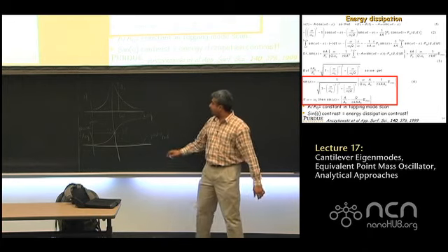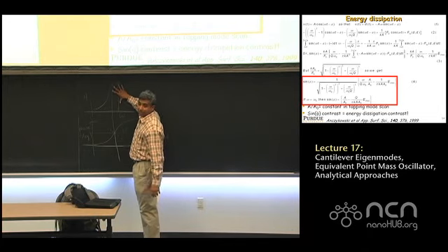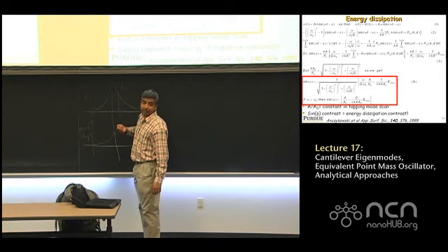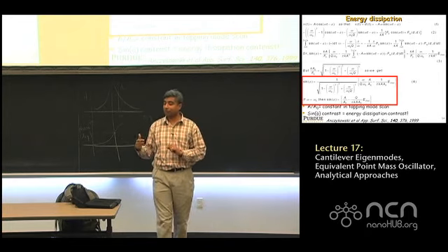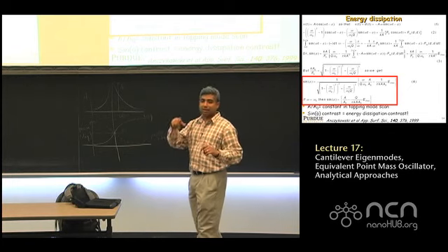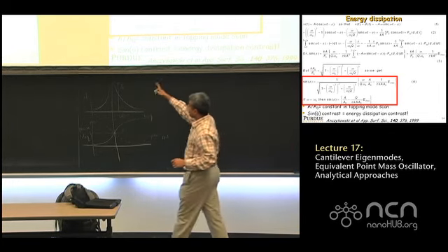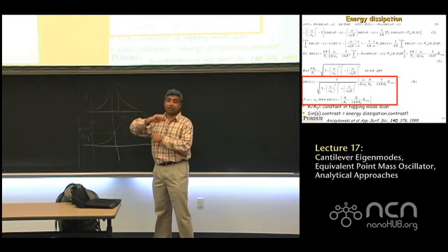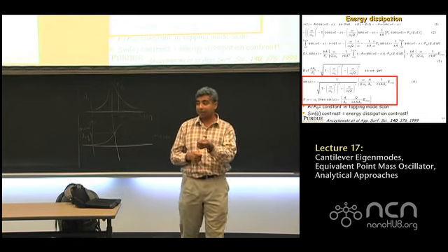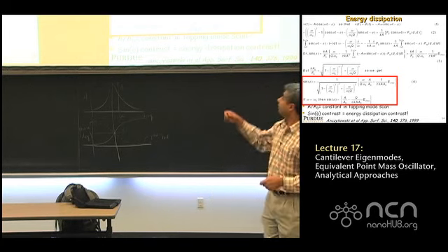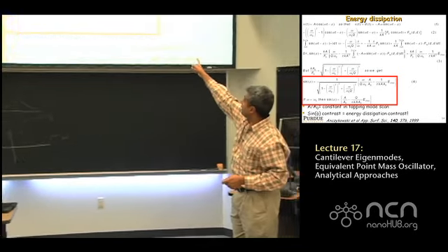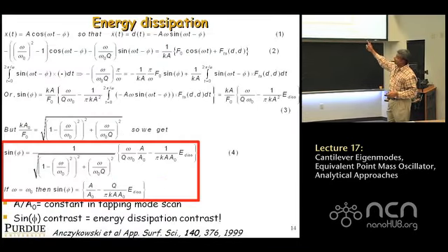If you know this amplitude A0, then we know what force you're applying, because we have done the transfer function before. Remember, the magnetically excited transfer function relates the amplitude you get to the driving force. You can invert that, and you can get the driving force F0 in terms of the drive frequency and so on as shown. So kA0, or F0, comes from that analysis that we did without tip-sample interaction forces.